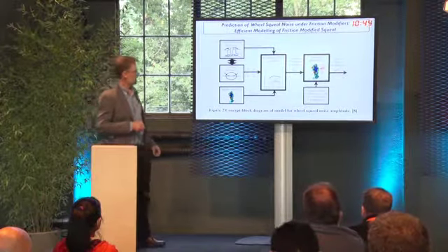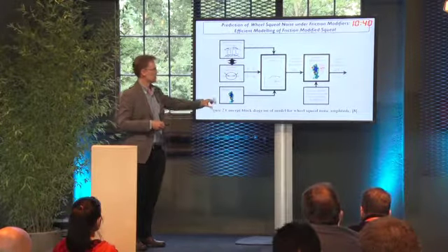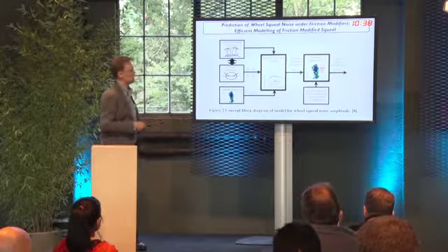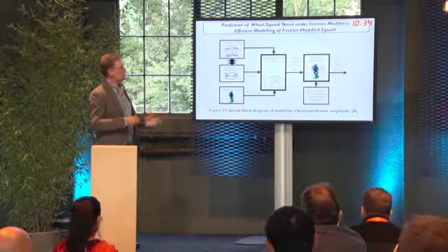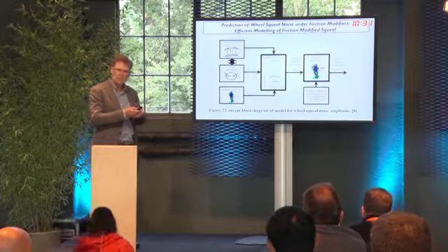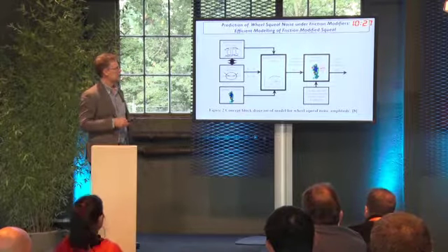So we pick out a suitable mode, or we can look at multiple modes, getting excited by that lateral creep curve. I'll talk about a squeal limit cycle analysis, because the squeal is an exponential growth to a nonlinear limited amplitude, and that's the amplitude you hear. So it's a limit cycle analysis, and that vibration gets transmitted via acoustic mechanics to the ear.